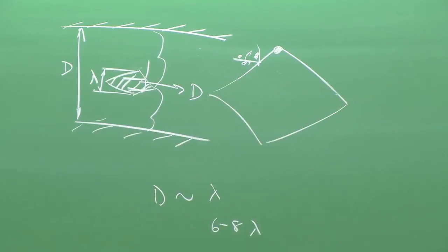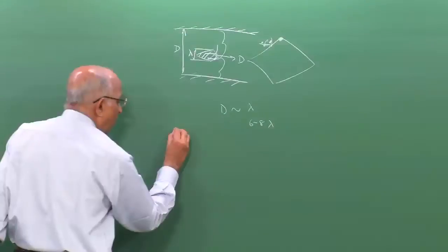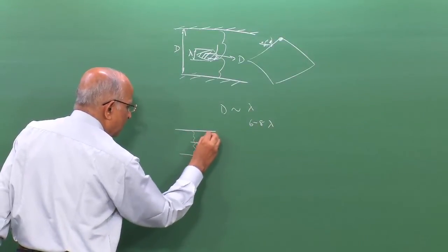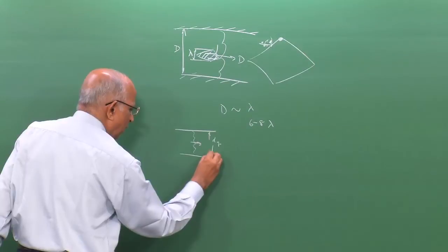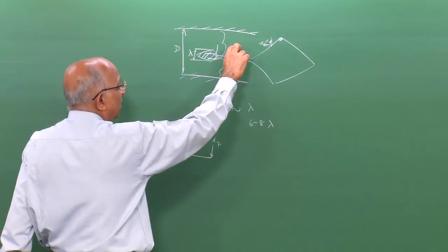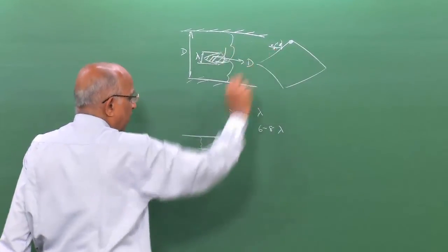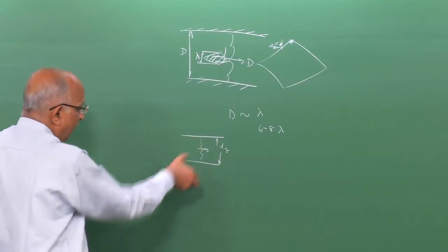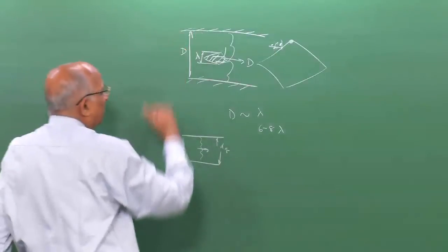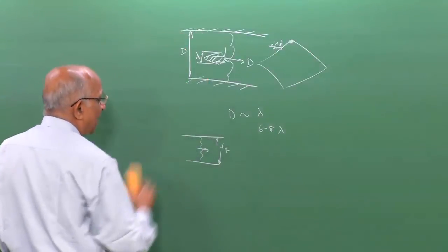Another thing which comes in: when we had a flame, what did we find? A flame propagates in a pipe and we had something like a quenching distance for a particular pipe. We talk in terms of a critical diameter, or the failure diameter, of a pipe for propagation compared to the quenching diameter of a pipe. In addition, some nice experiments have been done with detonation.